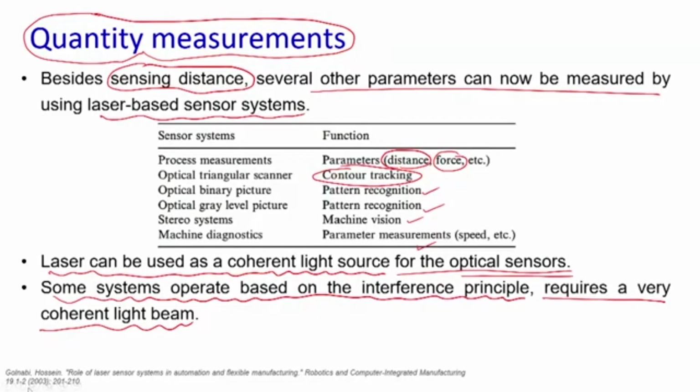So, lasers are very useful to generate 3D topographical data, and based on that we can compute various parameters such as the surface roughness, its Ra values and Rz values. Not only the surface roughness, based upon this interference data you can also find out form errors and a variety of other geometry or form parameters of the surfaces.